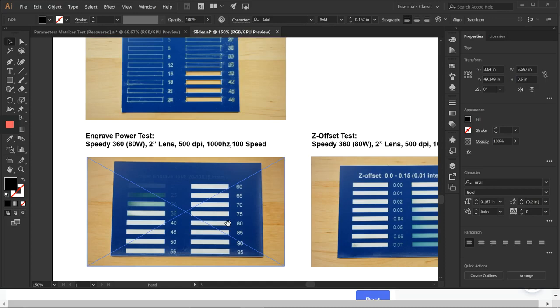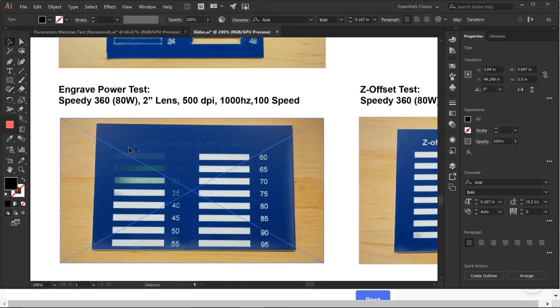Next, I did an engraving power test. You can see at the very top with 20% engraving power, you don't get much of an etching. Once you start to use 35%, you get a surface etch, but the detail is lost. Around 40 to 50%, you get a nice white engraving that is just surface engraving. But once we use too much power, that's when we get all this white residue from engraving the white instead of the blue, and it makes Trolley's quite difficult to clean.